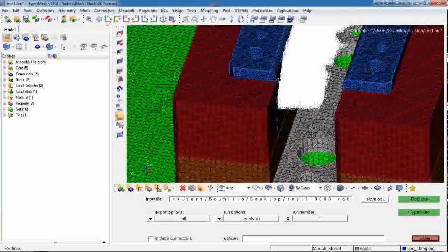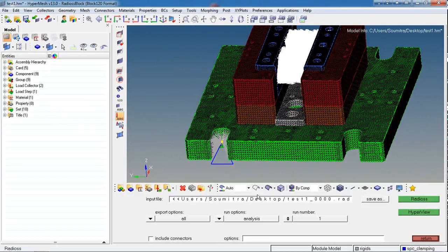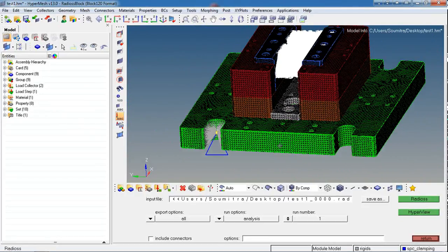The most probable errors that can occur are the meshing quality, the Jacobians, and maybe the skew errors. They are to be carefully solved. After that, the contact establishment is very important. That can be a difficult task, but still using the basic FEA, which uses automated contacts, you can easily do that. After that, the most important step is the mapping of the loads, that we have done using the die module, die stress analysis process manager.